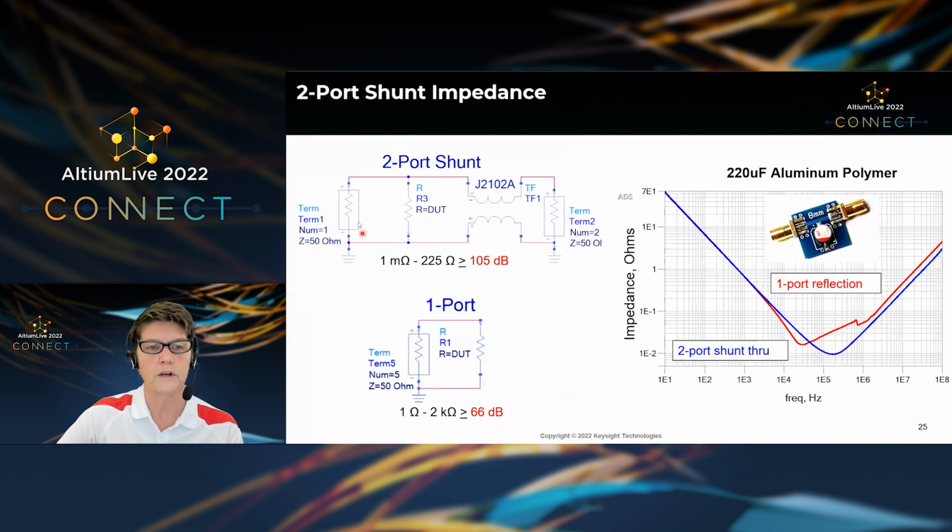And the way the shunt connection works is that instead of in series between port 1 and port 2, the impedance that we want to test is actually taking the signal line that goes from port 1 to port 2, and we're shorting it through that very low impedance to the ground connection. Now, the way this measurement works, you'll notice that in order to do the measurement, we have to be careful that there's no ground currents. The network analyzer assumes that port 1 and port 2 have the same ground potential, and so we actually oftentimes have to put a common mode rejection transformer in here to prevent currents on the ground rail from corrupting our measurement.